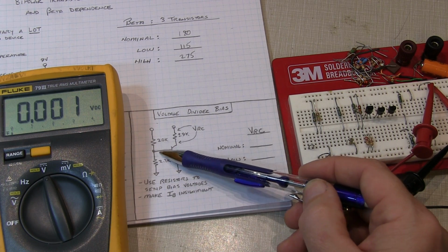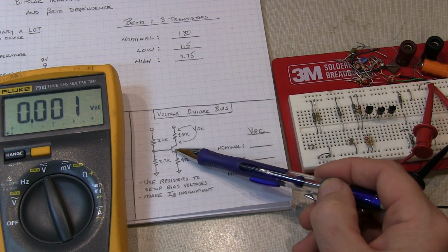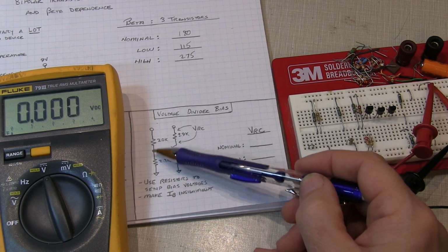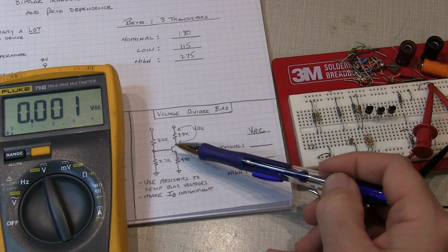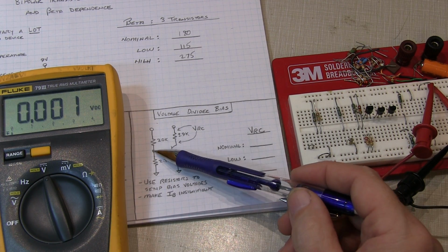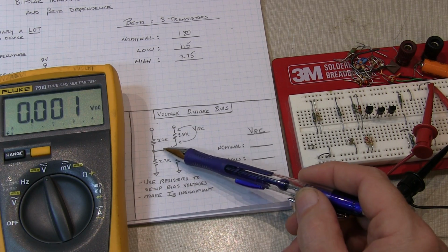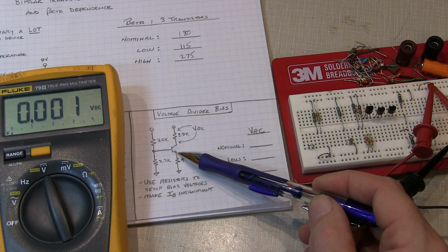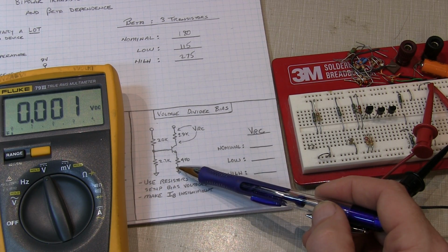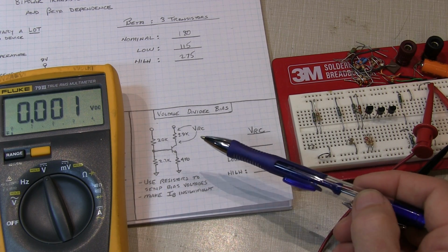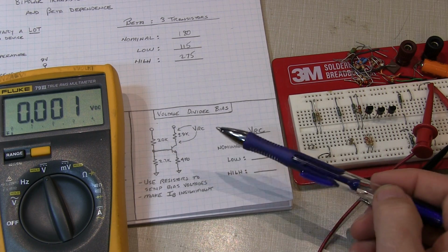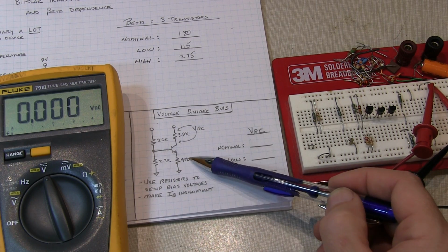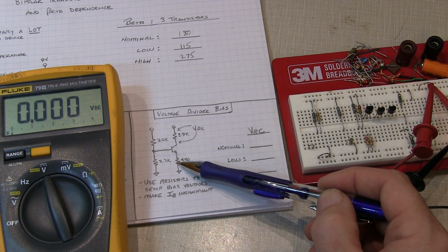So any changes in base current that are a function of beta are not going to affect this voltage divider much. So this voltage here at the base basically stays pretty constant even if you have a change in base current or a change in beta. So with that fixed voltage at the base, it also establishes basically a fixed voltage across this emitter resistor because VBE is going to be relatively constant as well. So with that fixed voltage on VBE, we can basically pick this resistor value to set up the current that we want here.